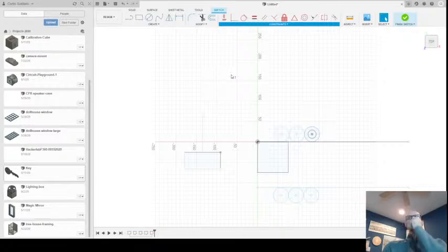Collinear. So this constrains two or more objects if they share a common line. This could be a line and a rectangle where the line and one edge of the rectangle lie along the same line. And again, the line is that indefinite ray, going indefinitely in either direction. It's not just the line we're drawing on the screen. It's the concept of the line that is drawn between 2 points. So collinear, let's demonstrate this.